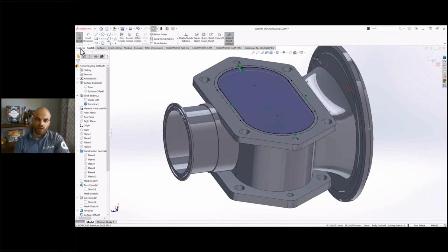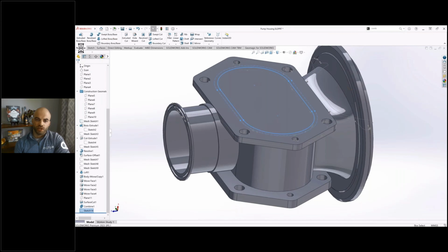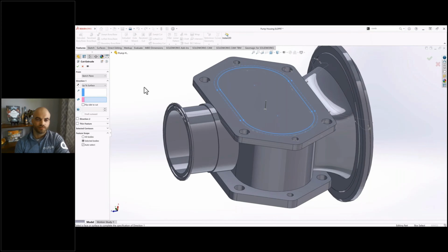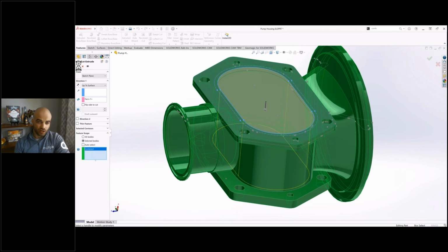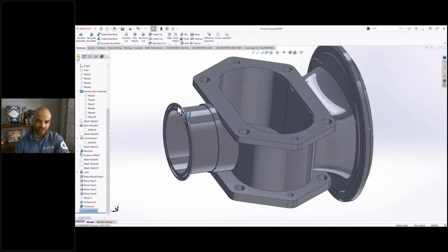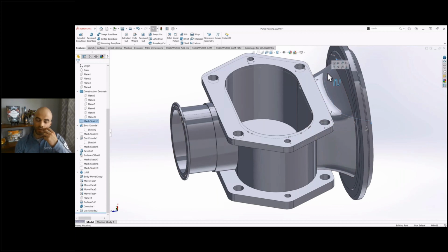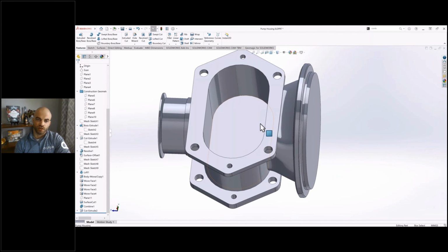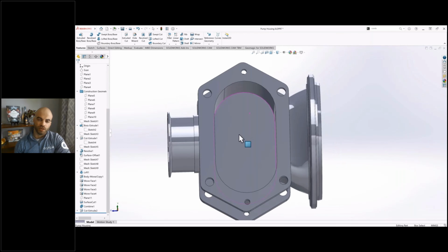So it's similar to the loft where I'm doing an offset of that profile just to make sure it's perfect and it has the correct wall thickness there. And then this is another idealization. I believe this is actually a little too shallow. I think it needs to be a 1/4 millimeter or 1/2 millimeter deeper, but I'm calling it equal to that outer flange face because that's close enough. And that's really what the design intent most likely was. We're trying to have that piece be a single thickness, right?